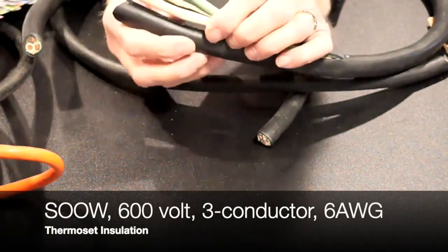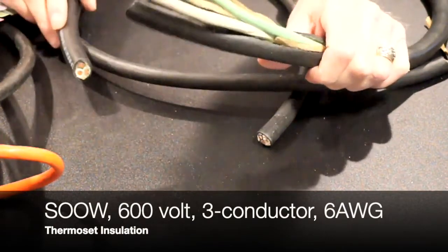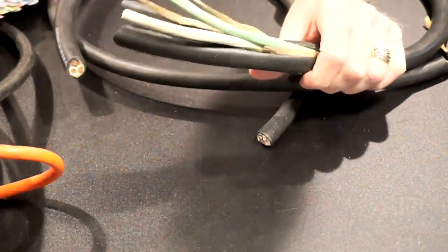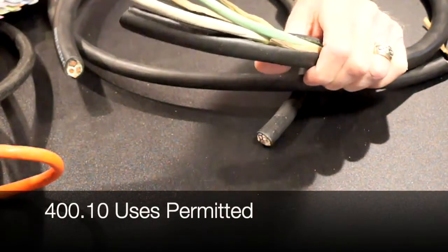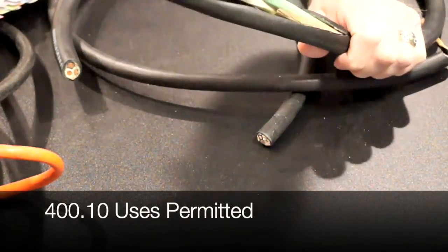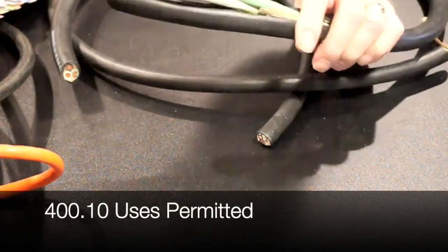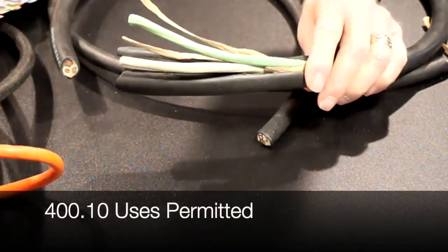And then finally, it gives me my usage, typical applications for this. And it says it's good for pendant or portable usage. It's good in damp locations with just the SO, but that W suffix on the end tells me it's suitable for damp and wet locations. So of course, that's very important to me then.